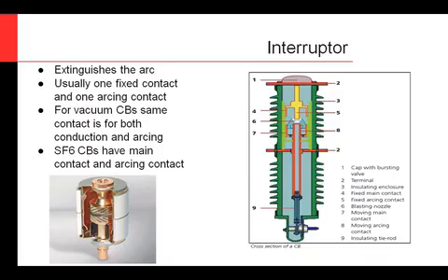That's these plates. Now, SF6 has a different design, where you actually have a separate main and a separate arcing contact. The main contacts are made for when that circuit breaker is closed. They're just there to conduct the current, have as little resistance as possible, and keep the current flowing without heat. Usually the main contacts are some kind of silver-plated copper. Whereas the arcing contact is designed to take all the heat and all the energy during the arc and the interruption process. So the arcing contacts are usually maybe a tungsten copper alloy or something where it can take this high amount of heat.